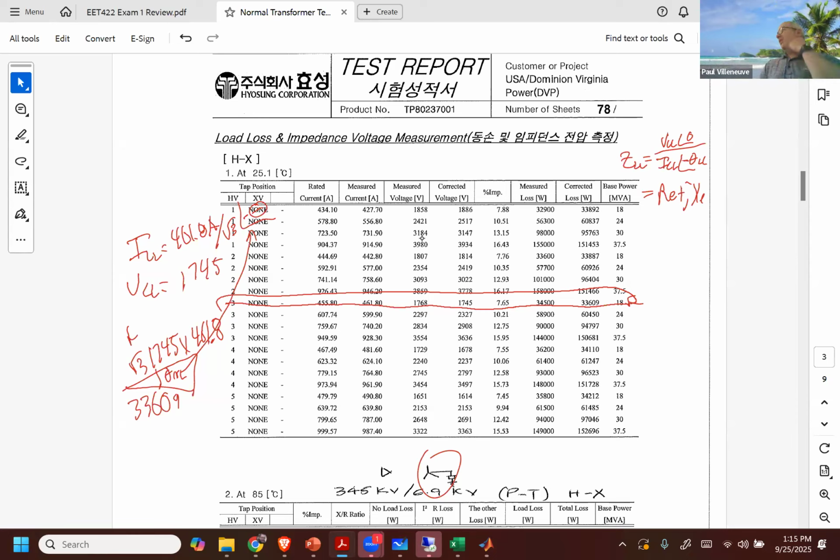So again, it's the same thing over and over again. It's just that for the load loss test, we do everything in series because it's the value of Z, right? We're looking for those series impedances. Whereas when I do open and short circuit, or the open circuit test, I do it in terms of Y. You can certainly do what we did in class. We did V squared over P to get the value of R, but I find it's just as easy to do it this way.